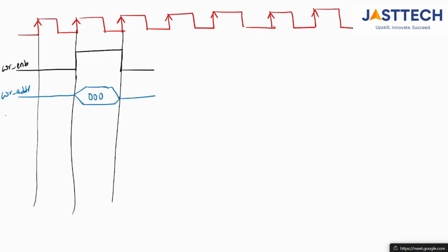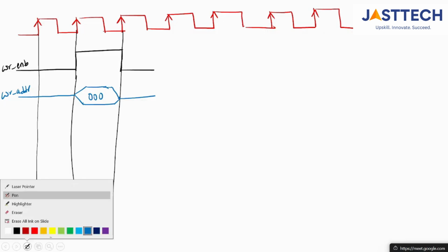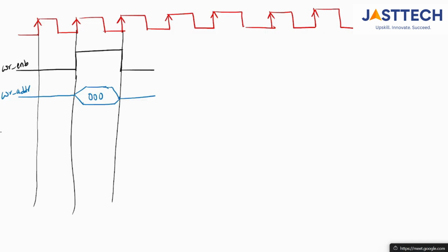And after that, next is data in, data underscore in. We need to provide the data, no? So what type of data do you need to write into the RAM? Let us take this is 8 bits of data. Let us take my data is 8'b1111_1111. For readability I'm representing it like this. 8 bits of data. So the write operation is completed.